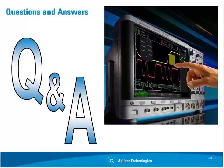So if you don't want to see the noise that's really there, you can use the method I talked about earlier of intentionally slowing down your scope's waveform update rate. But in my opinion, I want to see what's there, even if it's extremes that are not pleasing to the eye. At least it's showing me what's really there. The scopes that are updating slower are masking or hiding what's really there.